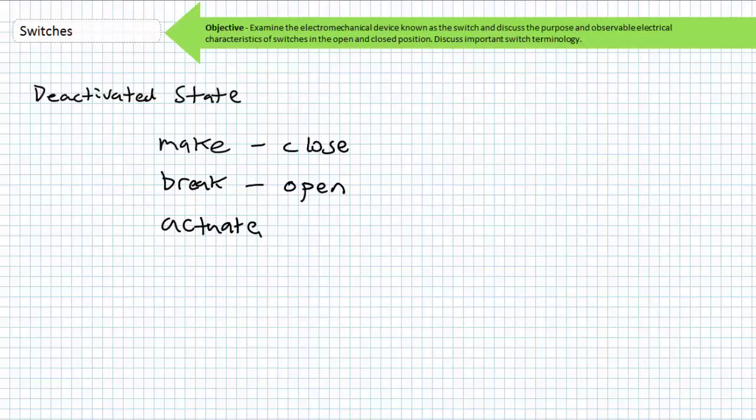The switch, prior to being hit, punched, poked, flicked, twisted, diddled, or dorked with, had a natural deactivated state to begin with. All schematics, all the time, are always drawn in their deactivated state, a point I will come back again and again to belabor in the hydraulics, electrical control of hydraulics, and motor controls playlist. For now, you must simply understand and differentiate between the two mutually exclusive states of deactivated and activated.